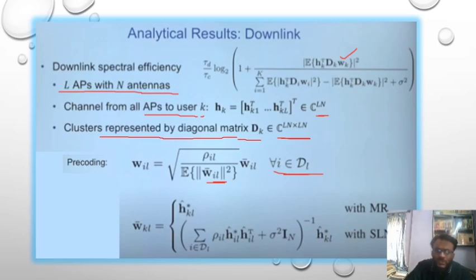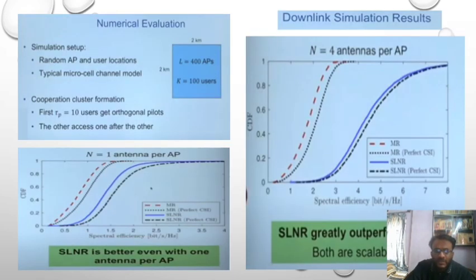So I can estimate these values with the variance of these values plus the noise variance, where AWGN is normally used. And W_k is the precoder, which may be MR, maximum ratio, or it can be SLNR, meaning signal to leakage noise ratio. Whichever it may be, as we will see in the last few slides, SLNR performs better than the MR techniques used there.